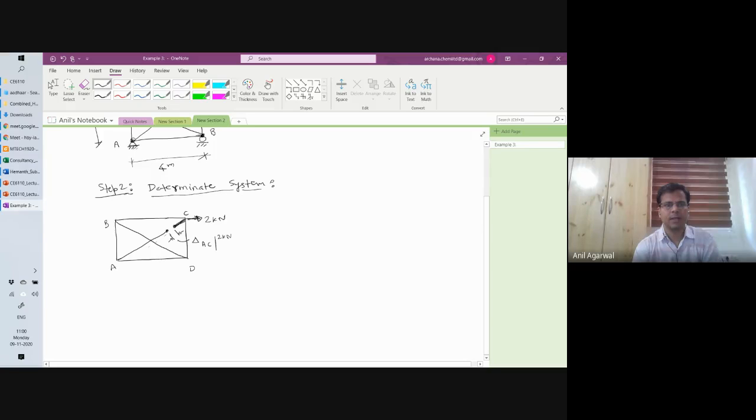So in member AC, I'm going to get a separation because I have cut the member and the member does not have a continuity. That means it cannot resist any load. This is a determinate system. But now what will happen is that this member that I have cut, that is basically one redundancy I have removed. But that actually was there.